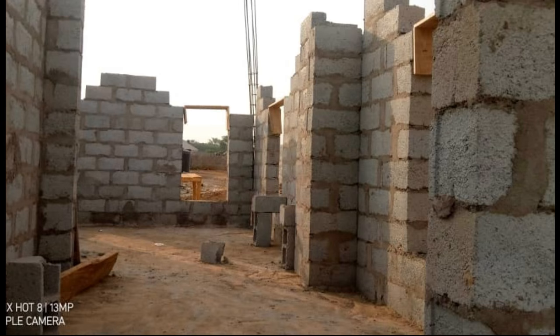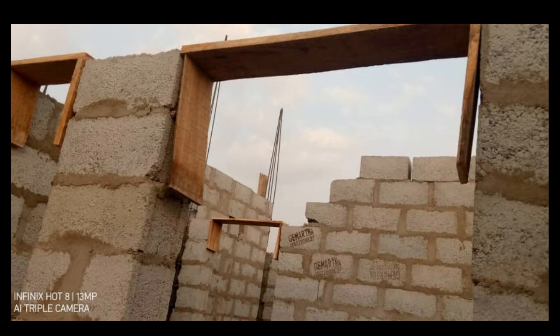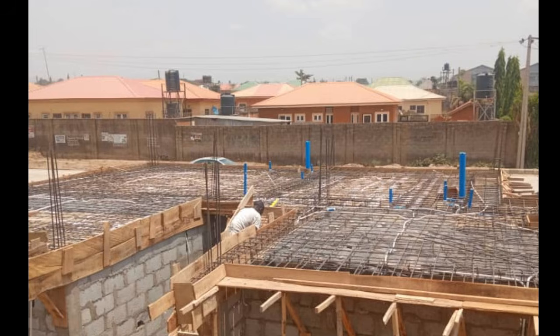Firstly, the block walls were set out and laid according to the architectural drawings up to the lintel level. Next, the formwork for the columns is now fixed up to the lintel level. The concrete for the lintels and columns were cast at the same time. Subsequently, block work continued to the underside of the floor beams location. Once the block work has reached the decking stage, formwork for the floor slab and beams then commences.